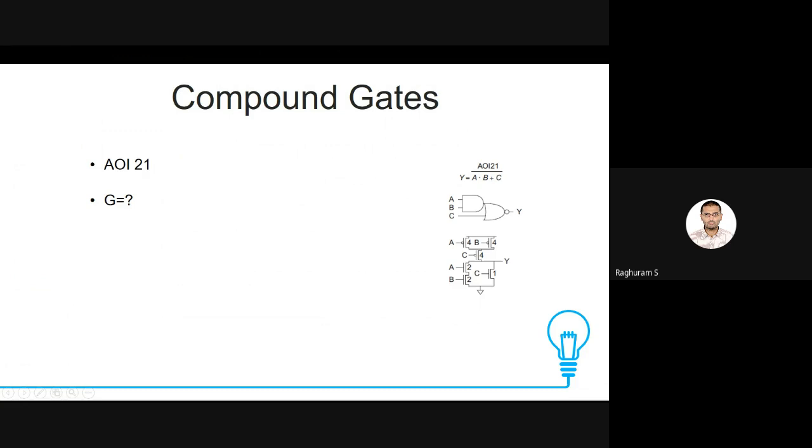If I put 1 1, I will not be able to get 1 for both of them in series, so I have to put 2 2. Same thing here, since I want a total of 2, I put 4 4, which is 4 4 4. And if you evaluate this pull up network, it will be equal to 2, which is unit inverter PMOS size, and this bottom will be 1, which is unit inverter NMOS size.